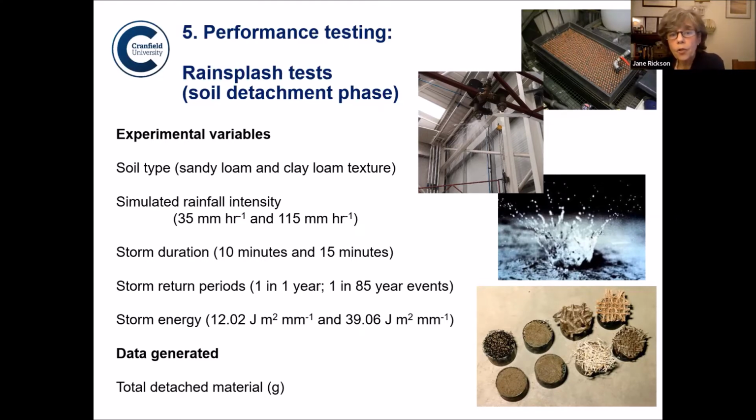Or we have our nozzle rainfall simulator, which has pressurized water being forced through a nozzle of known geometry that will then again produce a nice uniform cone of rainfall and of random drop size distribution, but again with kinetic energy that is similar to natural rainfall, so that we can simulate this raindrop impact on the soil surface.